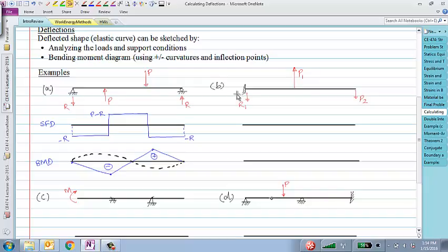And how about the moment? Which way would the moment be pointing? Counterclockwise or clockwise? Clockwise. Why clockwise? Well, one way to think about this is that if this was not a fixed support and not a free end, let's say if it was a simply supported beam and I had a big load in the middle, two equal loads at the ends, then this would want to curve up, right? If it wanted to curve up, and if I wanted to make the rotation at the left end 0, then I would have to apply a moment in the clockwise manner. Make sense? All right, so let's apply a moment in this way. Of course, I would need the values of the loads and the distances to calculate the actual value of M. But here I'm just trying to show you intuitively how you can do these things.